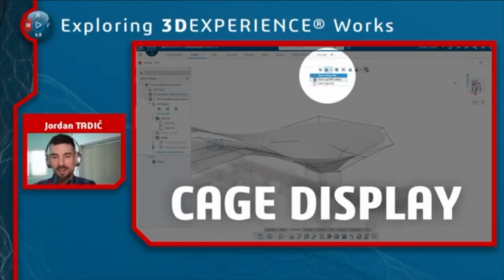That can be explained because what we're actually doing is aligning the cage entities to that sketch geometry. Because I have the bottom edges creased, that bottom face is flat. But if I wanted sharp corners so that it followed the shape of the square bracket, I would have to crease the vertical edges at those corners as well.